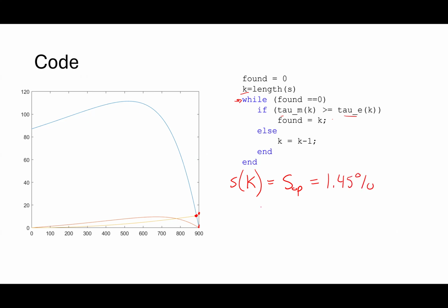All right, how would I figure out the speed then? How would I convert that to a speed? I'd say my synchronous speed minus my mechanical speed that I'm actually operating at, divided by my synchronous speed. All right, my slip is 1.45%.